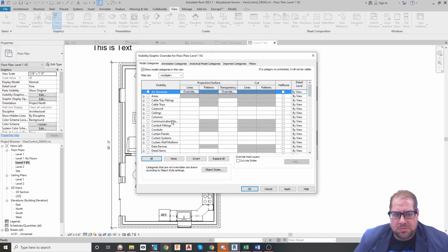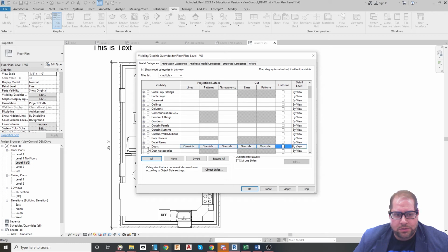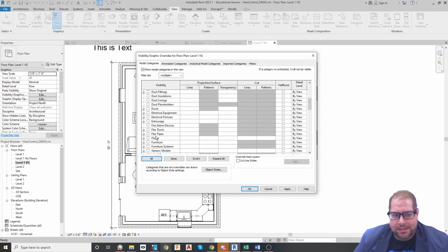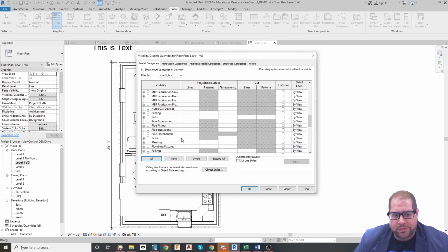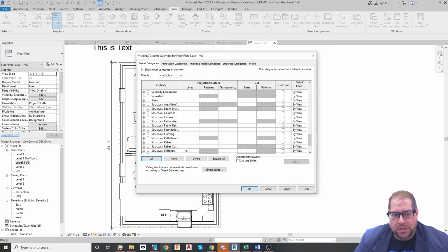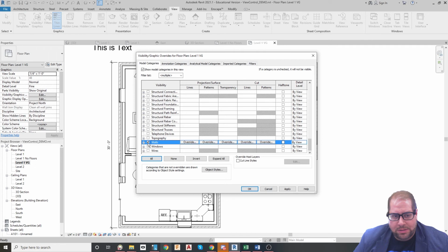I'm just going to mess with the model here, and I'm going to make sure I want to see areas, doors, lines. Lines are important for reference planes, and also lines are important for area plans for showing the boundaries and stuff like that. So doors, areas, lines, walls, and windows are what I want to see in particular here. I want to hit OK.